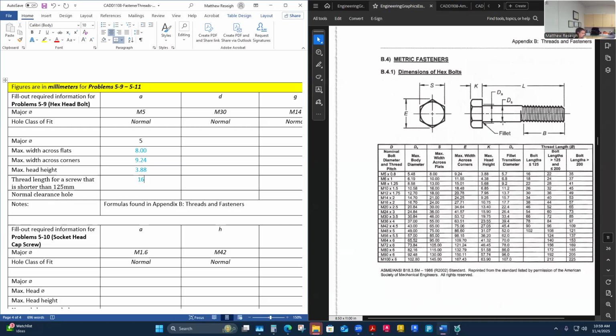You just have to be careful when you're designing that you don't end up designing around something that isn't threaded all the way. And then it's pretty common that if you need one that's threaded all the way, they're just going to be a little bit more expensive probably. And then you might be limited. The longer screws get, bolts get, it's more common to find that they're only partially threaded. The shorter they are, they're usually fully threaded. So just watch for that. It's just kind of a thing. And they show that clearly in their drawing.